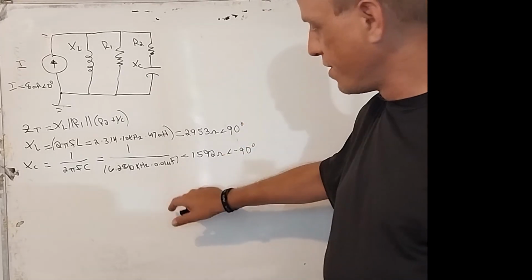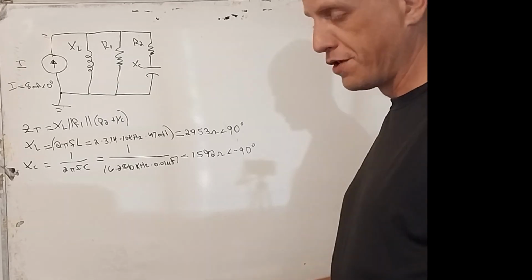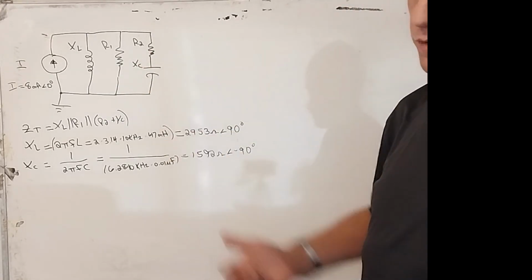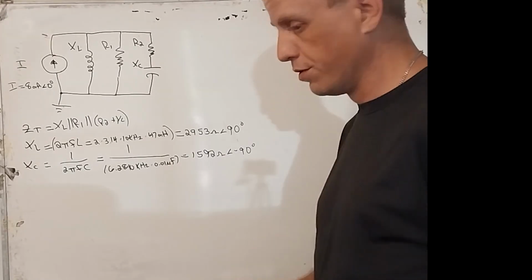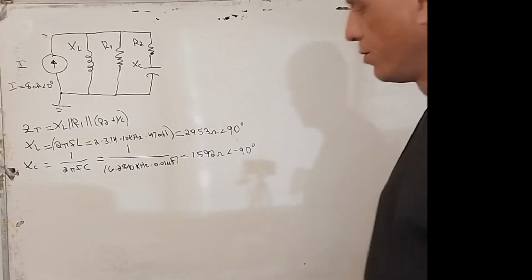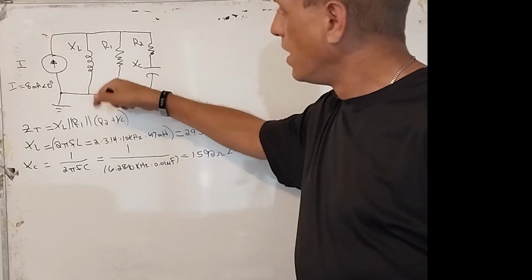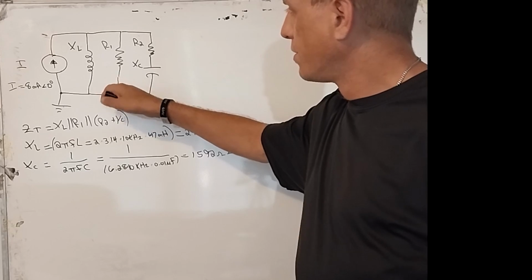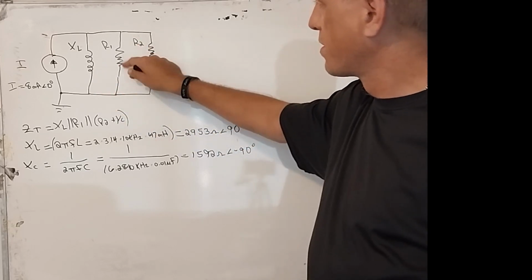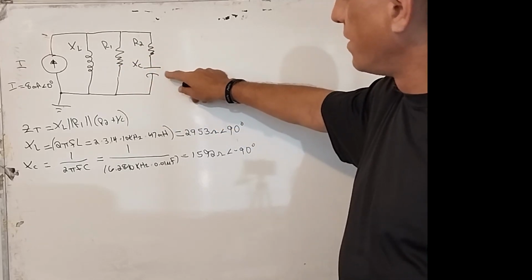Also, with the function generator, when I plug its power into the breadboard, and I have a circuit built with resistors, inductors, and capacitors, they act just like the inductive loads would at a real factory by theory, and the math works. So it's the same thing that happens in a building that's got an inductive load, and you got some computer that's got some load that's always running, and then you have some capacitive load that's doing something.